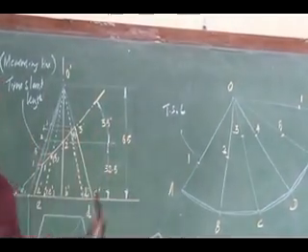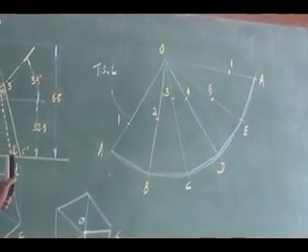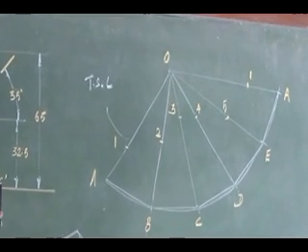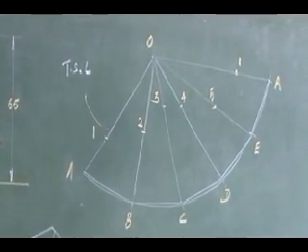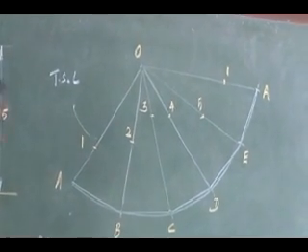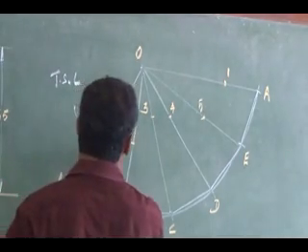Now you connect these cutting points with a straight line or curve. You have to connect the cutting points as a curve only for cone and cylinder. So just connect these cutting points as a straight line.